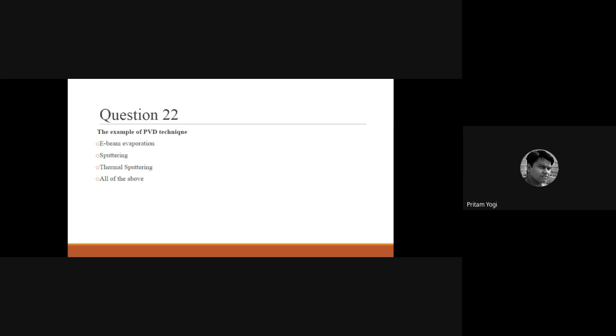Okay. So in every PVD process, we first need the vacuum system, like a bell jar or any vacuum chamber. For that, first we have to vent the system if we have earlier used it in high vacuum.